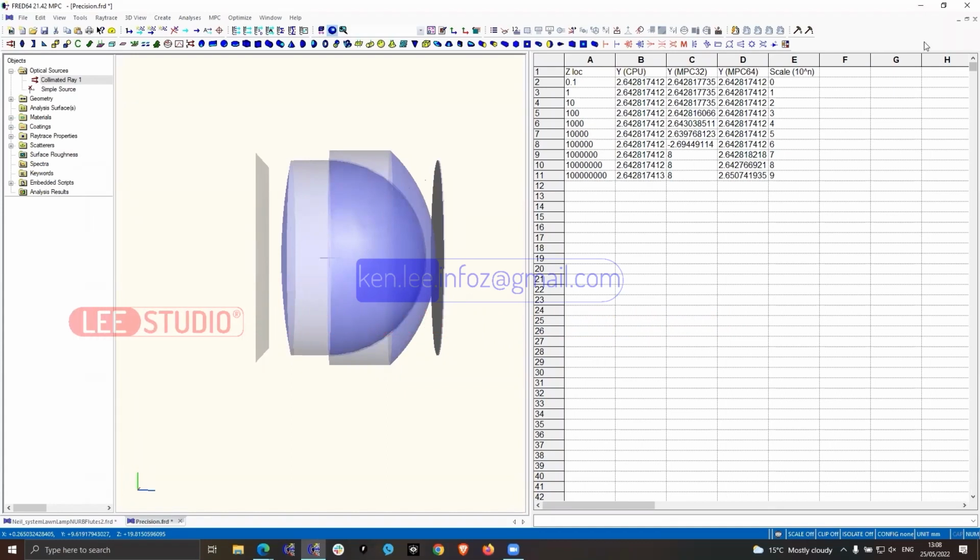Then you see the ray height calculated via the single precision trace and via the double precision trace. You can see that the single precision trace gives you nice accurate numbers up until a length scale difference of about 10 to the 5. Then the calculation breaks down, and single precision calculations just can't get us the right answer anymore when the length scales are so vastly different. But with double precision, we get the right answer pretty much all the way out to a length scale of 10 to the 9, which is essentially what this graph highlights.